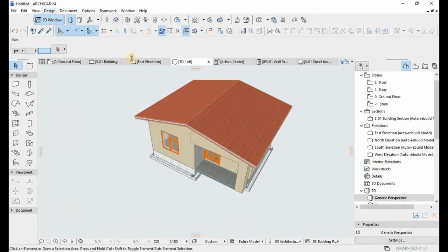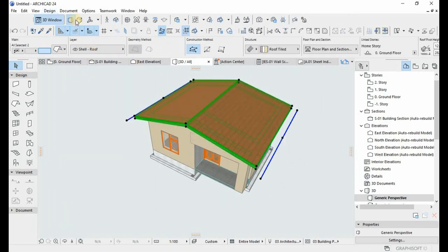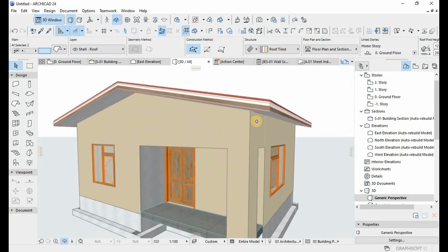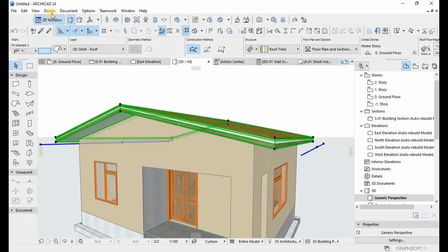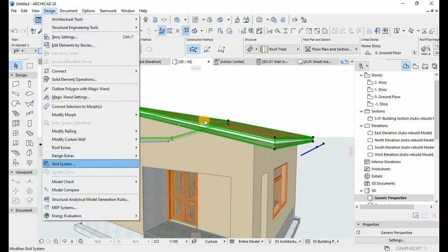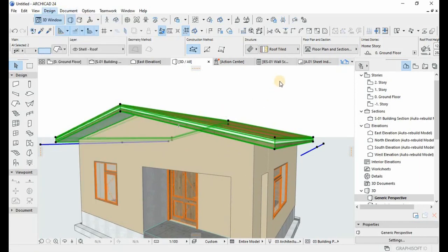This is just for organization of your models, guys. Organizing your model elements. Layers are just metadata and have value and purpose. Very, very important for later on, when you're creating layer combinations and saving views.